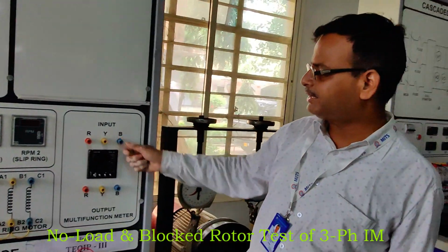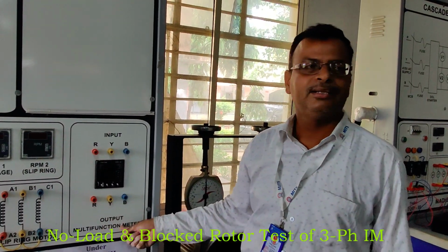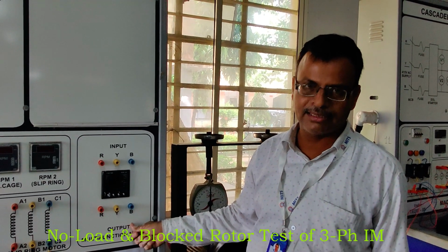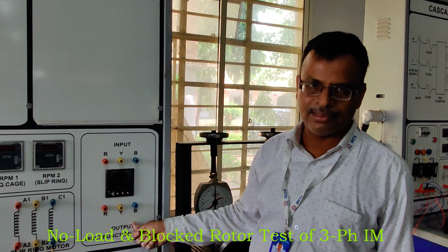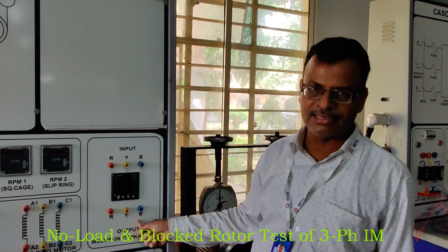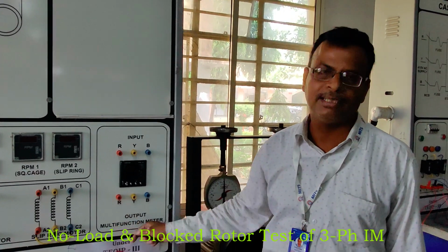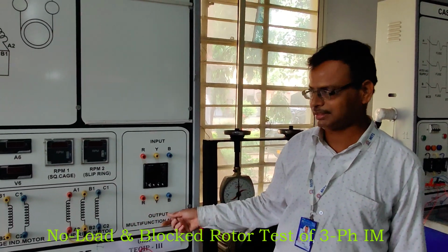It is called multifunction because you can measure all the electrical quantities like current, voltage, power factor, power, reactive power, frequency, line to line voltage, everything, with the help of this multifunction meter. That's why it is called multifunction.